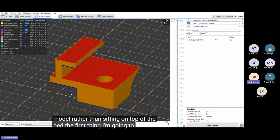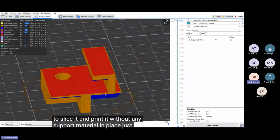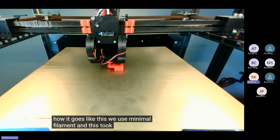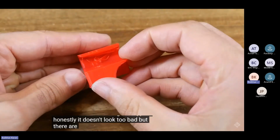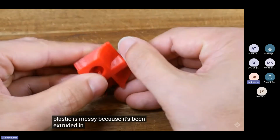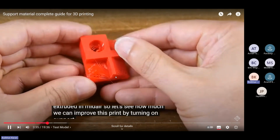The first thing I'm going to do is to slice it and print it without any support material in place, just to see how it goes. Like this, we use minimal filament, and this took just under 15 minutes. And considering no support, honestly, it doesn't look too bad, but there are droopy sections where the plastic is messy because it's been extruded in mid-air. So let's see how much we can improve this print by turning on support material.